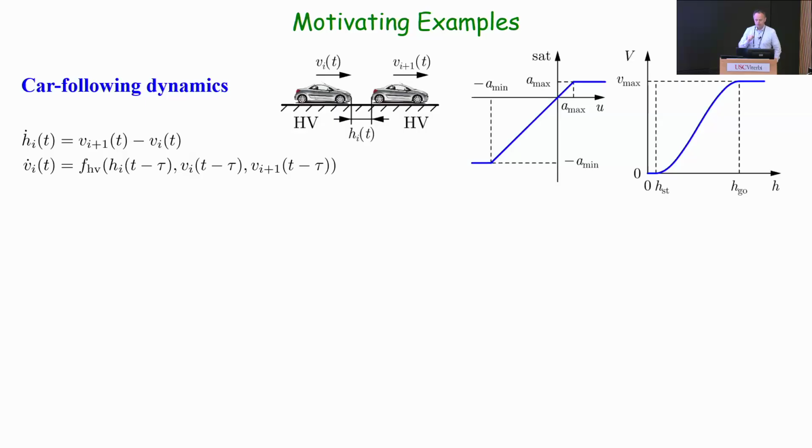Okay. So once you model the system, then you start to see something very interesting. You start to see the interaction between the time delay, the fact that you are responding to the vehicle in front of you with a certain delay, and that, in the case of a car, is typically around 1 second, right? So that's the difference between you seeing something and actually putting brake torque on your wheels.